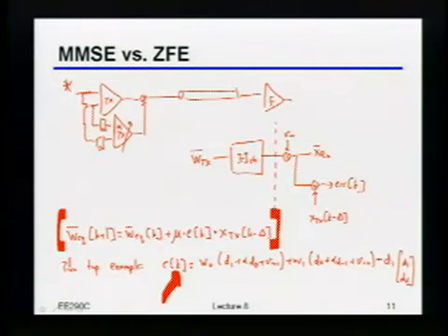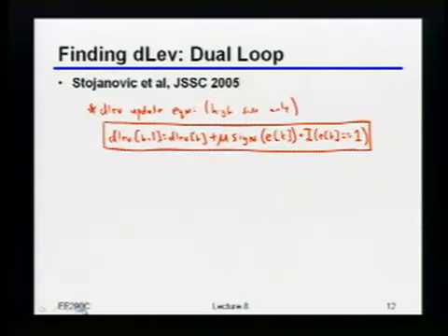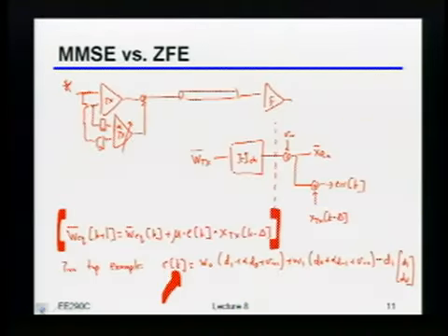OK, so unless there are more questions on this, now we can... there are more questions. Great. Yes? Can there be more than one point of convergence? OK, so yes. Now this is starting to get into some of the technicalities. If you really do the sine-sine version of the loop, there could actually be more than one point that you converge to, because the only thing you're really enforcing is that, on average, the number of ones is the same as the number of zeros.